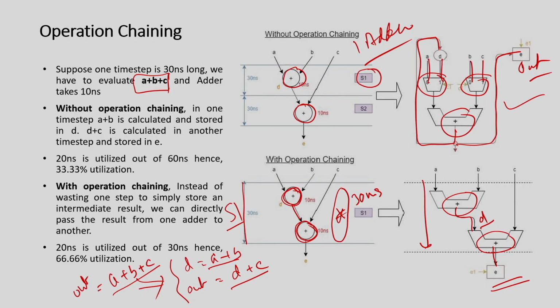If the timing is satisfied, for example the target clock is 30 nanoseconds and there are 2 adders in chain, this path based scheduler will always schedule them in series so that they can be scheduled in the same clock. Since the objective is to identify the minimum number of time stamps, it does not look into the resource overhead, because if I schedule these 2 operations in 2 different time stamps, I need only one adder.